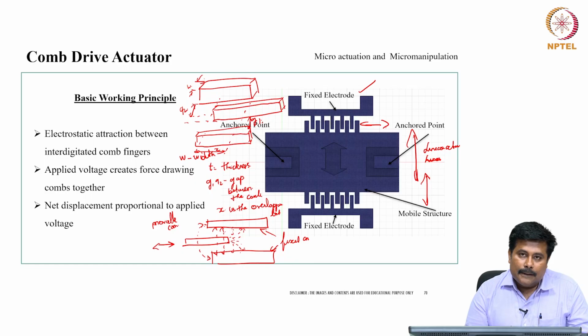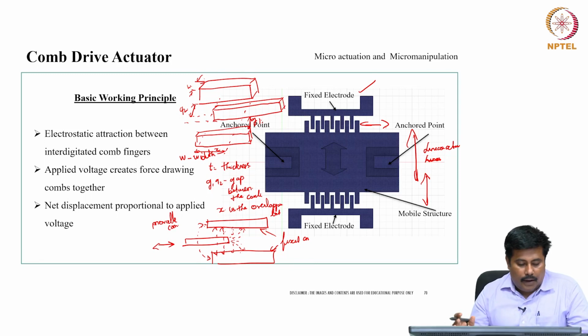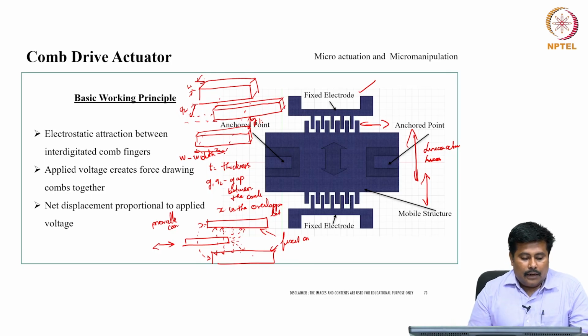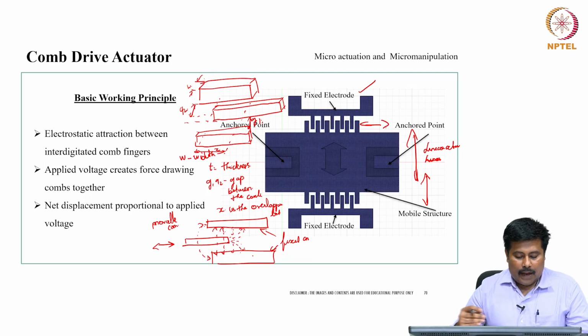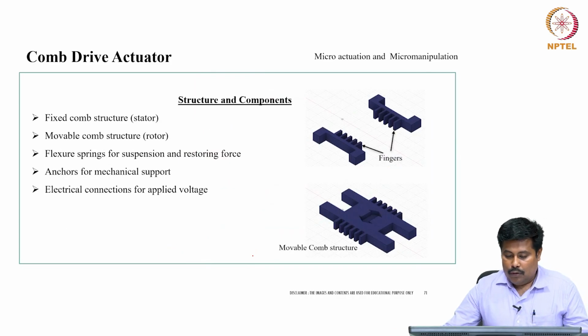So the biggest disadvantages of a comb drive actuator are a moderate driving voltage, the small offset in the direct current driving mode, and larger layout area. However, they can be compensated by a higher displacement rate than other actuators. A vertical comb actuator is used to have a higher and greater angular moment, and the design of the vertical actuator with the comb drive brings a higher deflection angle at a low voltage.